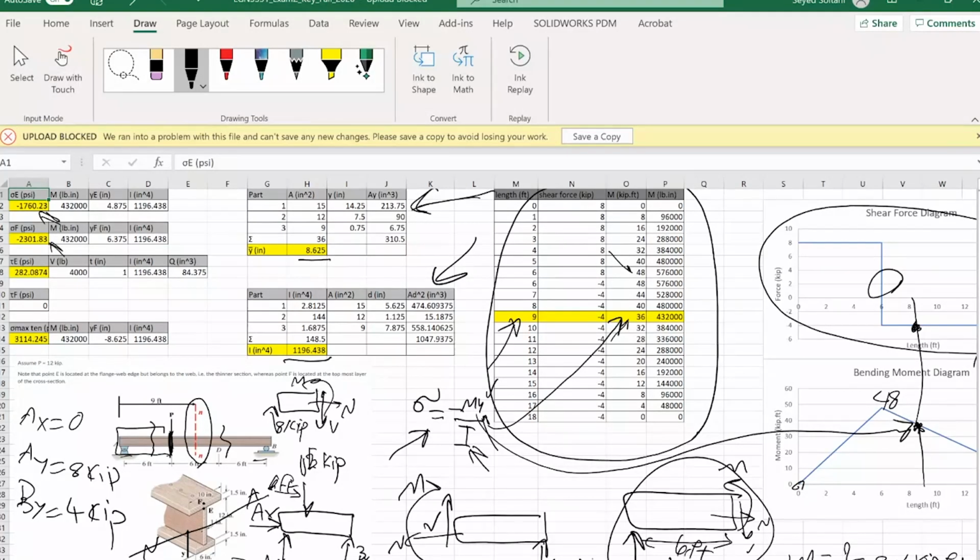And this is what I mean. When you draw the shear force and bending moment diagrams, you would use the units of convenience, I would say. And it's absolutely all right, because we don't want to get stuck with the numbers there. The overall trend and just some appropriate units would be all right. But when you want to calculate the stresses, then this is where the consistency matters most.